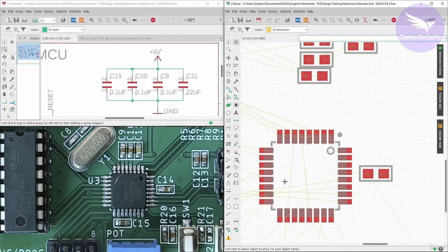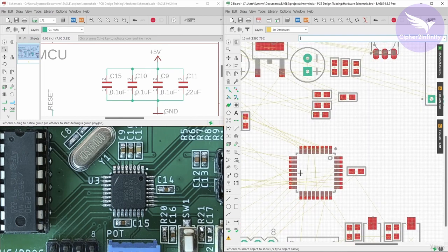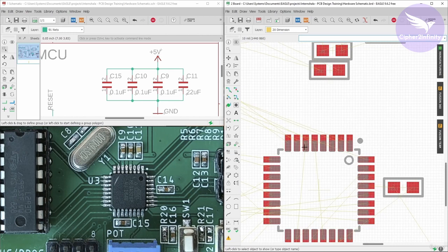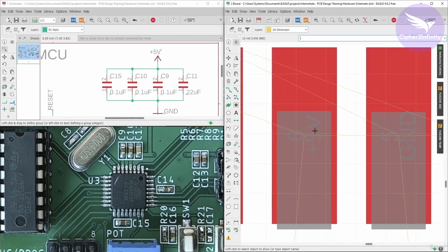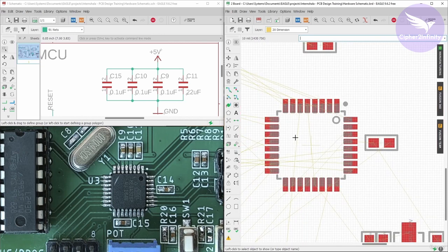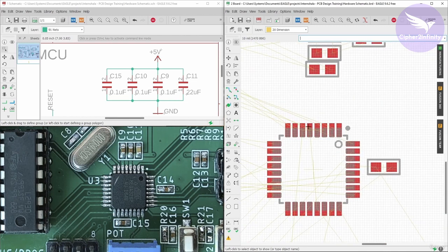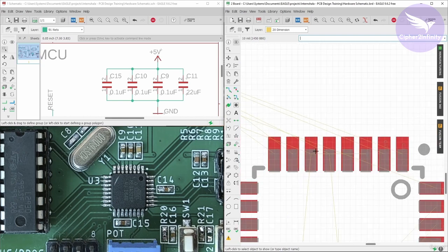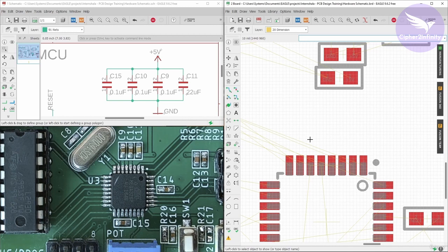There will be a lot of switches inside the controller, and when the controller is working, for example, if you are working on an interface at a high speed, there is a high probability that there will be noise on the plus 5-volt pin, because of the switching of the internal components, the internal transistors or MOSFETs present inside the controller. So there will be high frequency noise on this 5-volt line, and it's our responsibility to remove that noise, and we have to decouple that noise towards the ground with the help of capacitors.